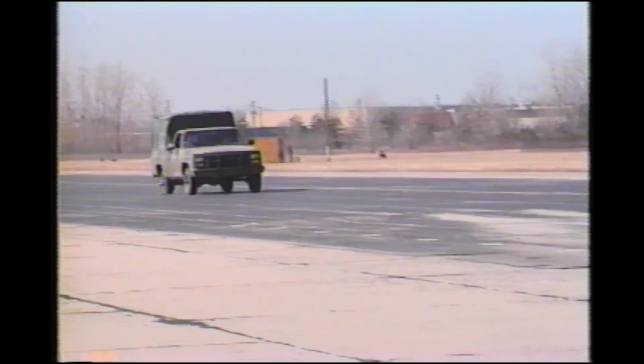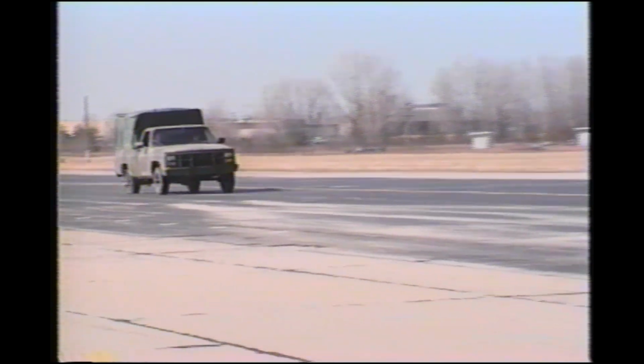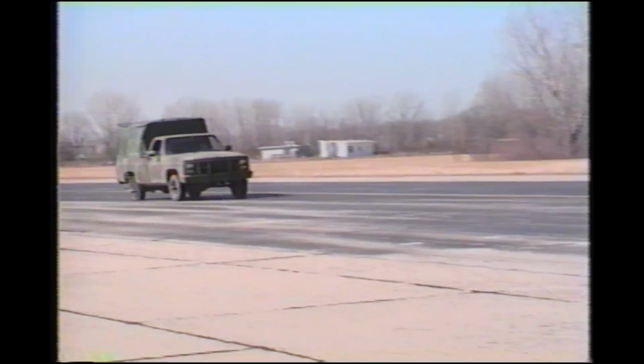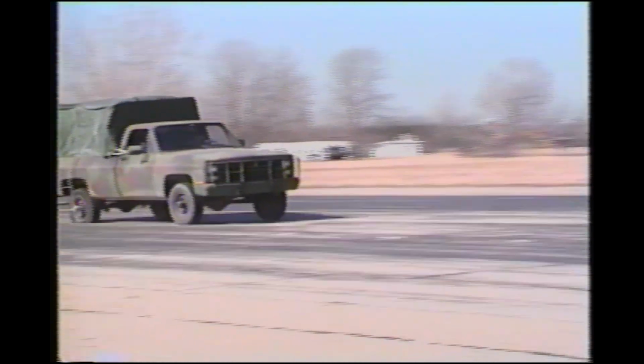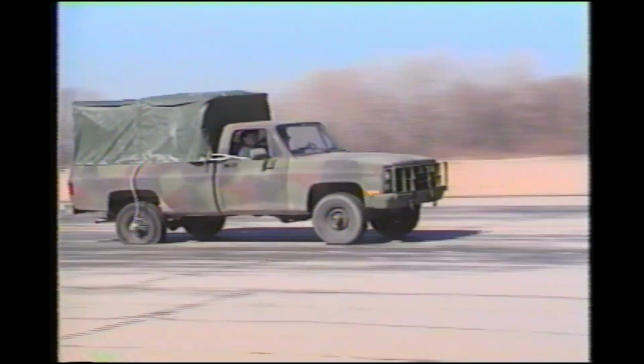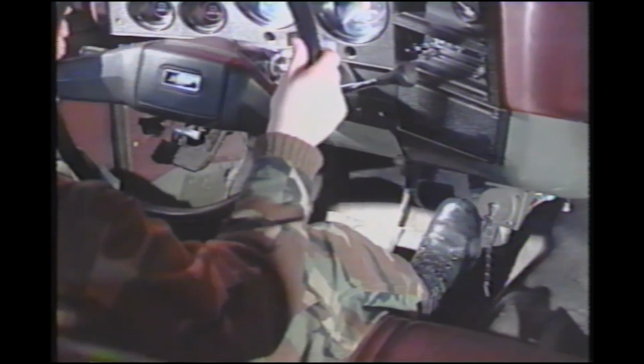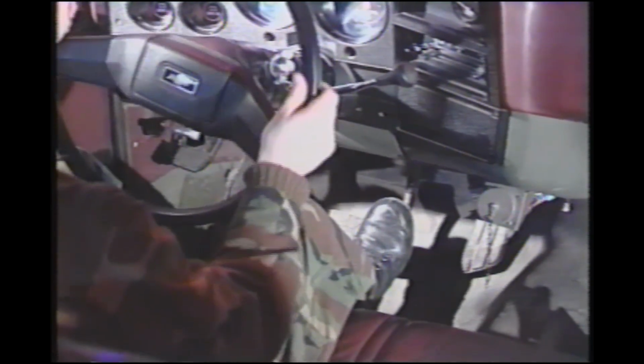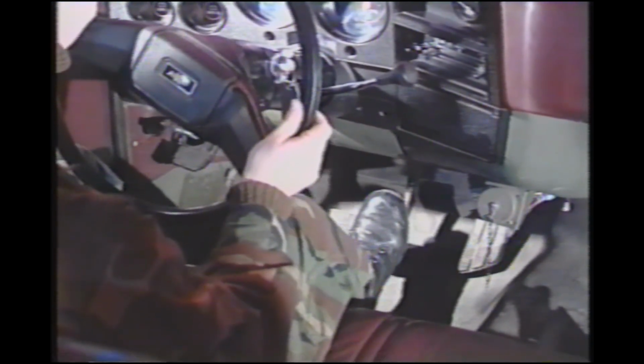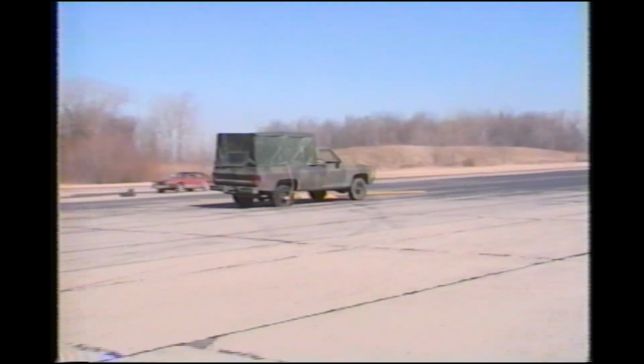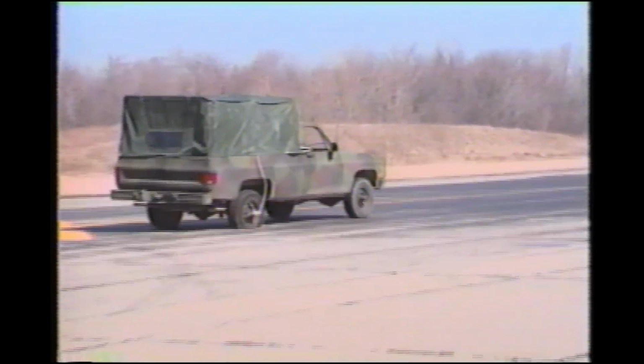If the vehicle has a blowout, don't panic. Do not slam on the brakes. This will cause the wheels to lock and send the vehicle out of control. Firmly grip the steering wheel while maintaining vehicle speed. Once the vehicle is under control, drive it to a safe area. Gently press the brake pedal and steer the vehicle off the road. You can maintain control as long as you don't overreact.